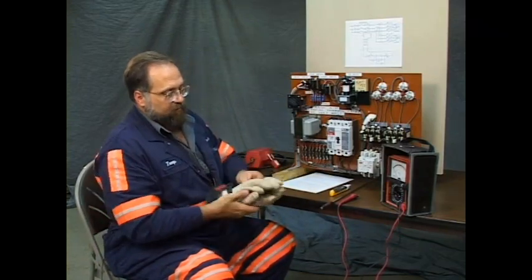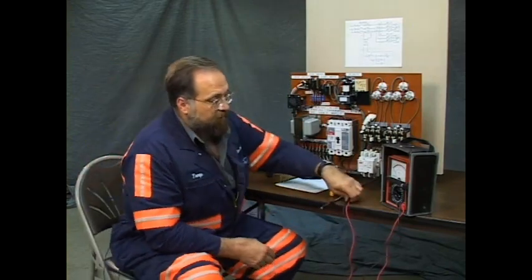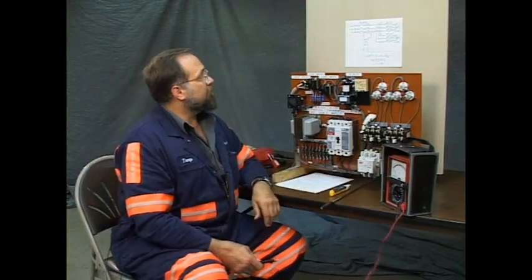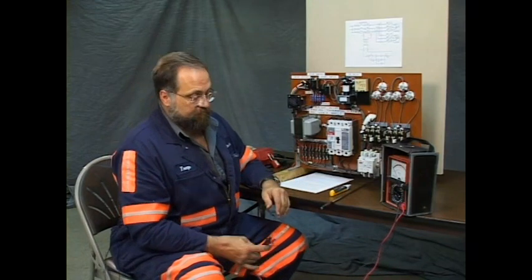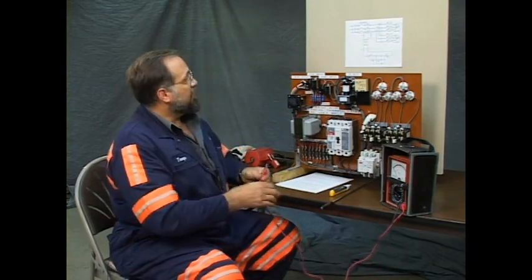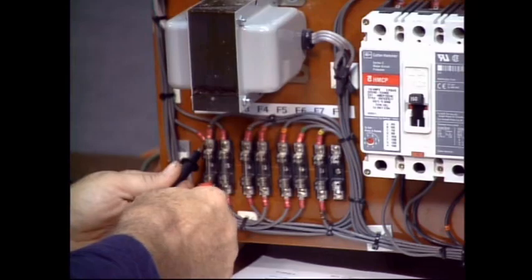As with the problems that went before, nothing will operate. None of the control circuit will operate. To avoid possibly missing the problem, you want to apply beginner troubleshooting. Let's start at the beginning. In the beginning, L1 was to the line side of the F1 fuse.